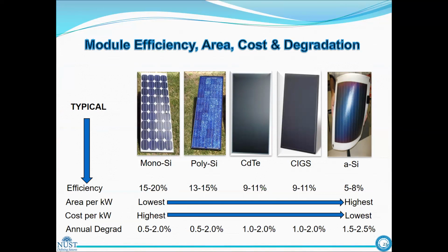Okay, another question, what times are considered for calculations of inter-row spacing? As we have already discussed, we should calculate this value for winter, when there is the lowest elevation angle of the sun and the highest tilt angle for the photovoltaic module.